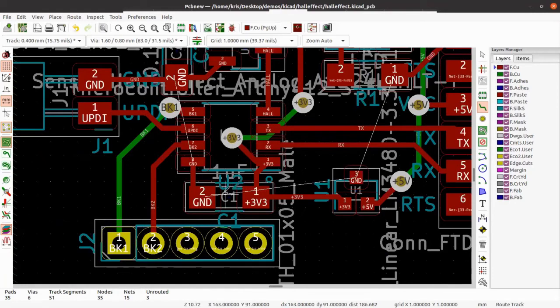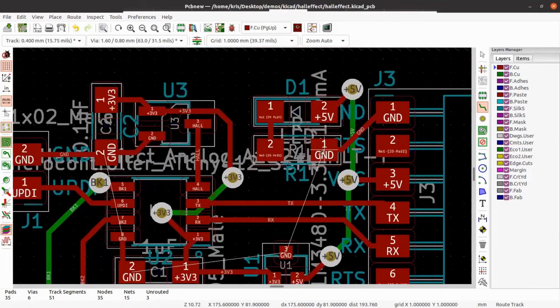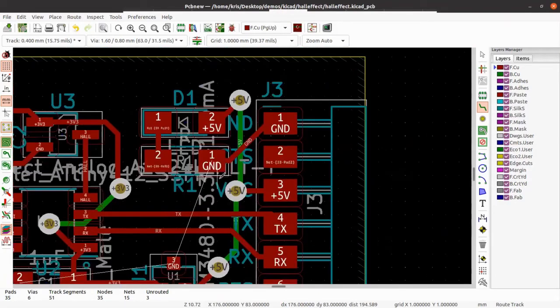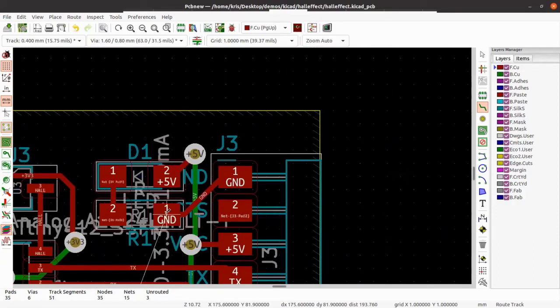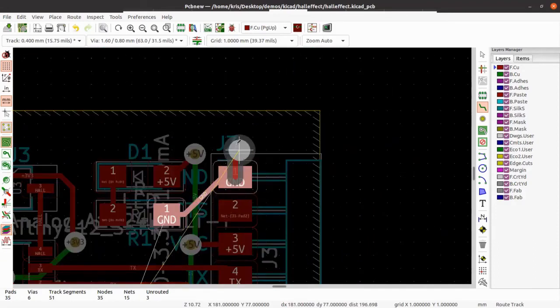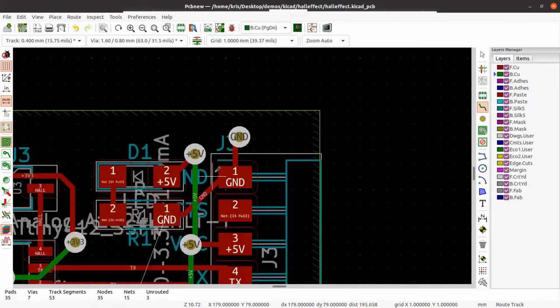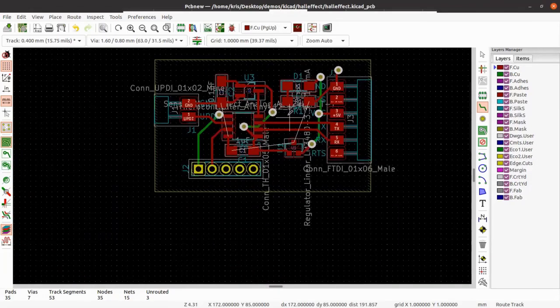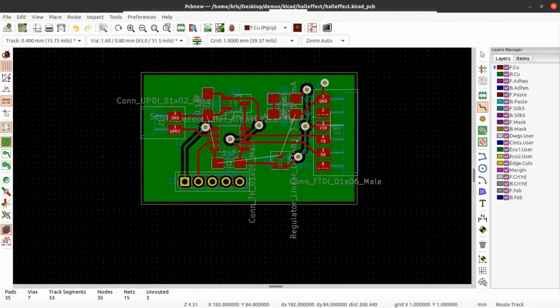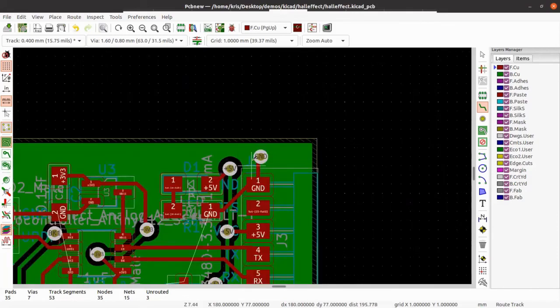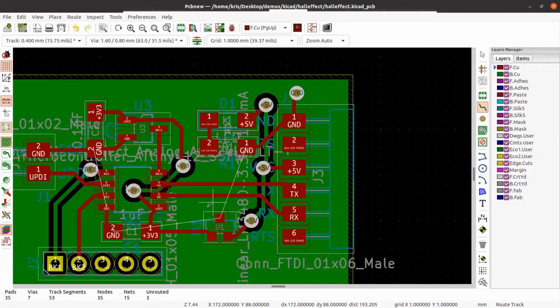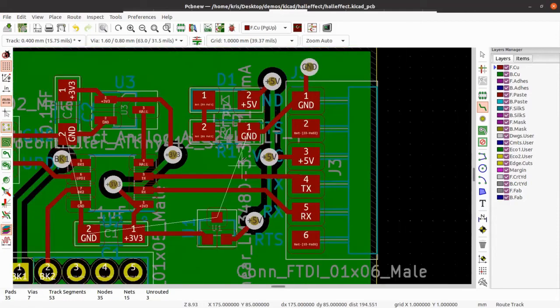And we need a via that actually connects to the ground layer from all the ground elements over here. So I'm going to start with one here. So I'm going to start drawing a via, then hit B. No, B to redraw. So now it filled up because it actually found the connection with these ones. And then instead of doing a bottom layer trace to the ground element over here, so we see that these are connected.